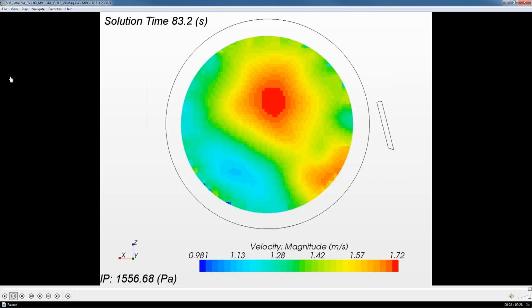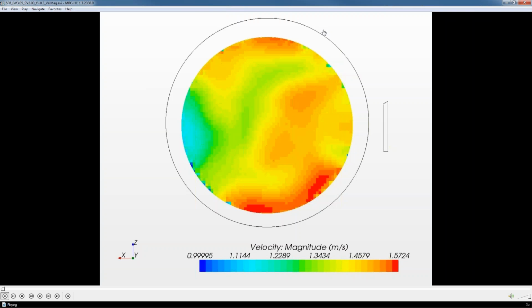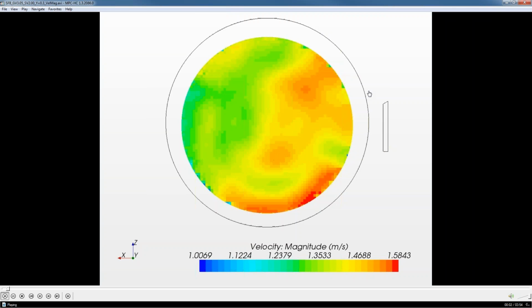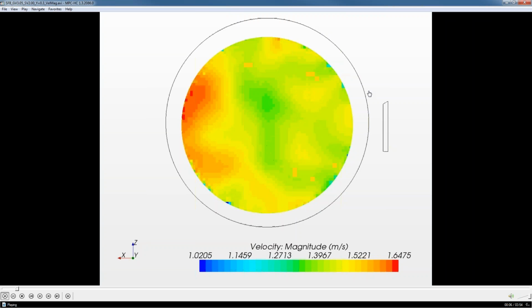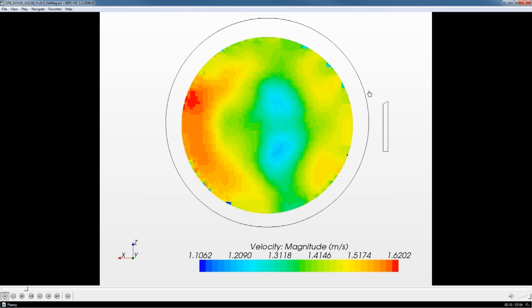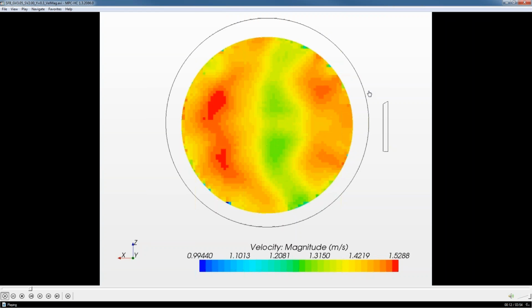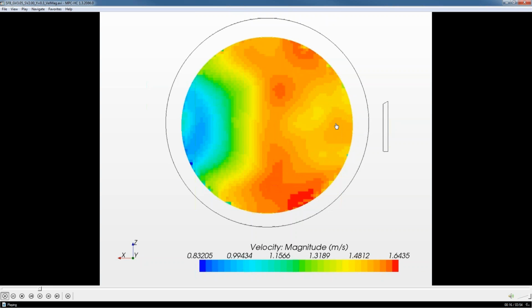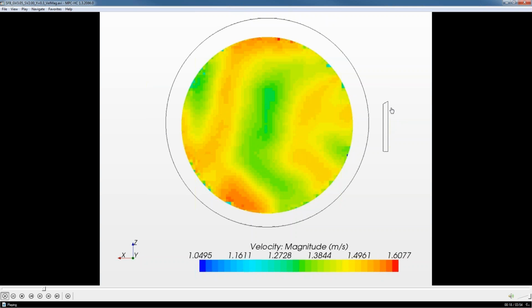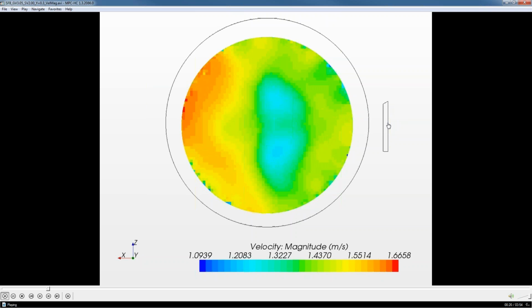And so what we would then do is if you actually straighten that out, you can end up with a really good unsteady but statistically steady distribution of airflow across that bed, which is going to give really good mixing and ensure that that actually works really well. And so this is just a really good example of A, poor duct design, and B, if you rectify that